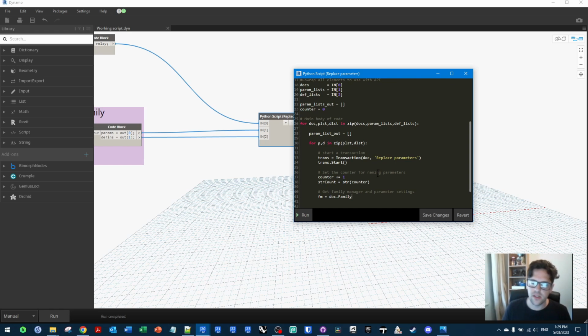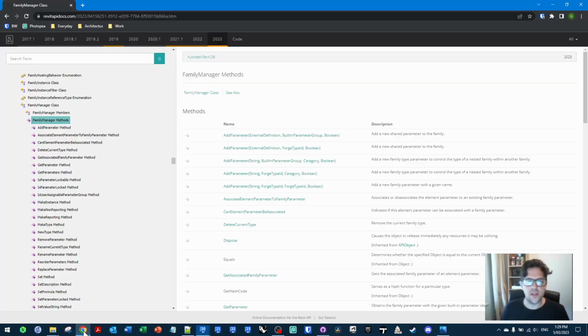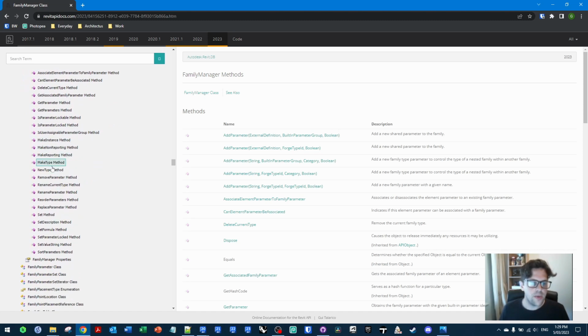So you're probably wondering at this point, what is the family manager? Well, it's really a special class in the Revit API that helps us do things to families. So rather than everything being separate, disconnected methods and classes and properties, Autodesk decided instead to give us one unifying class to do things to families, especially when it comes to parameters and types. So we can do a lot of things here.